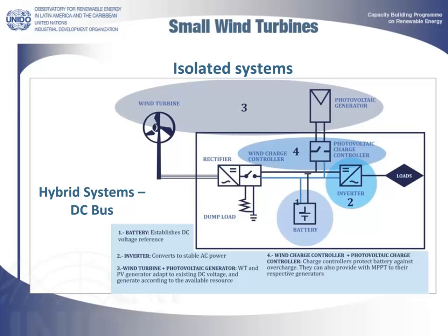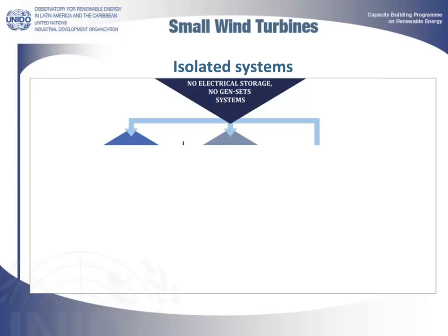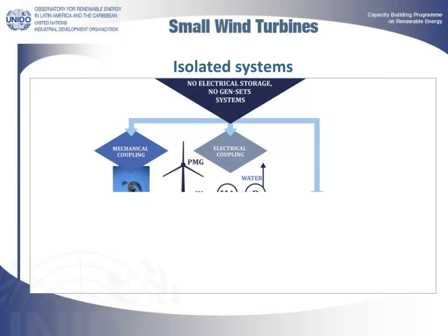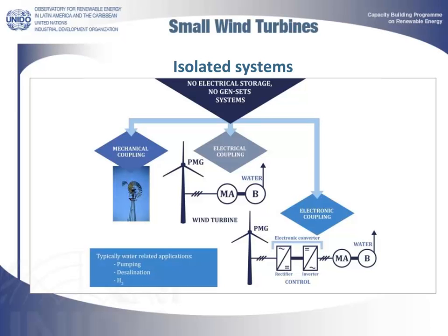In this case, we encounter the need to dump loads, whether useless or typically useful, such as pumping or water desalination systems. Therefore, these are systems whose most valuable result is often not electricity itself, but some other product that can be stored easily and inexpensively: heat or cold, and water. Desalinated or purified water, ice, water in reservoirs, etc., are typically stored products.